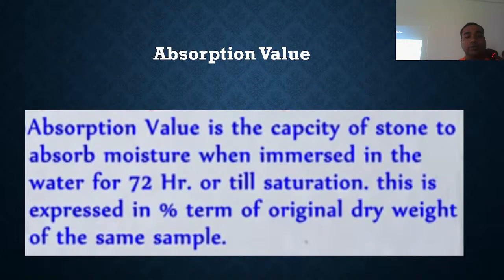Absorption value is the capacity of a stone to absorb moisture when immersed in water for 72 hours or till saturation. This is expressed in percent terms of the original dry weight of the sample.